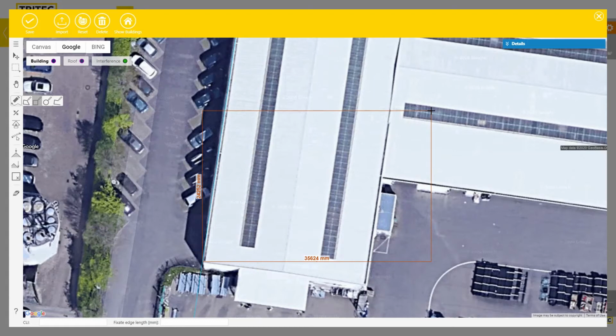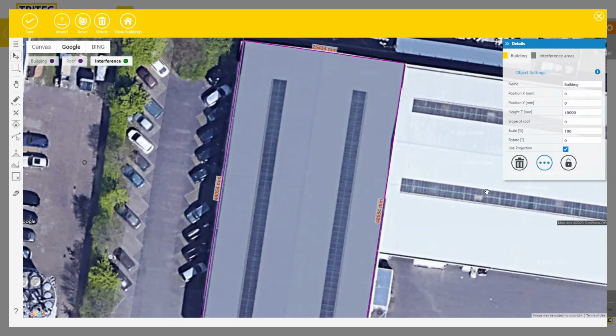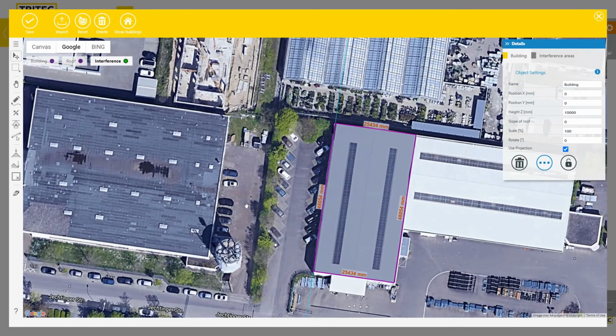Well, but what's now the use of the guideline? Very easy. Hit the shift key and keep it pressed, and now the rectangular and everything I do is oriented either parallel or perpendicular to my guideline. And now, this looks good. So now the roof is done.